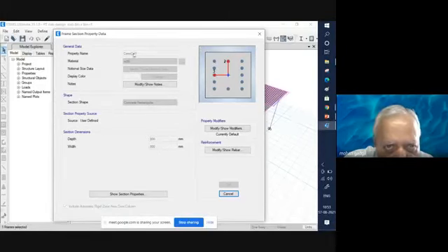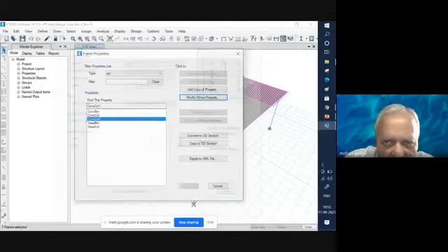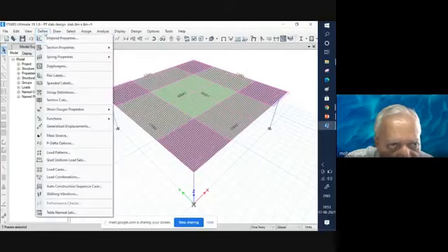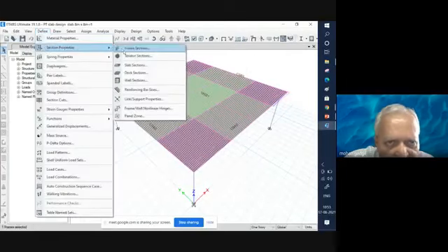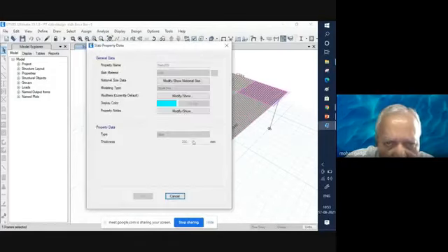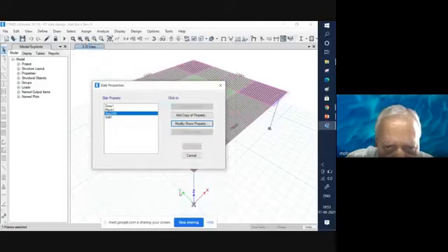The grade of concrete is M35 and so on. So this is the member that I have considered as far as the column is concerned. Similarly, I have defined the slab. For the slab, I have taken this slab which is 200 thick. You can have a look at that. So this slab is taken as 200 mm thick, and it is taken as a thin shell, and accordingly the behavior will be adjusted with axial compression and so on.